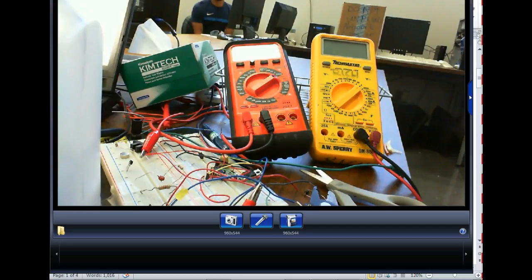So by George, if you come up here and you're trying to see the light and you look down the end of that sucker, you could be damaging your eyes, right? Y'all understand that? You can look at fiber in a fiber scope when it's inactive. If you don't know what the other end of the electronics is, and you're trying to look at it with a fiber scope, don't do it, because the other guy could be generating light pulses that you can't see, and it could be damaging your eyes. So be careful. Be careful with it.